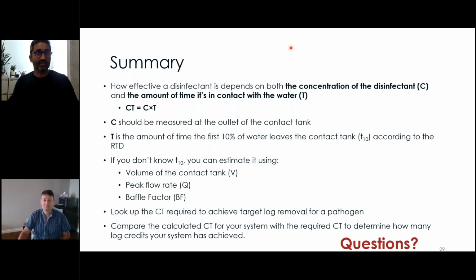If it's a small system, then maybe you have a large enough vessel that you can use to collect a volume of water, and then you can use a stopwatch to see how long it takes to fill up to a certain known volume. Based on that, you can calculate the volumetric flow rate. So the amount of volume that you're able to collect over a given amount of time, either a minute or some seconds, you can use to then calculate a volumetric flow rate. Off the top of my head, that's what I would suggest, depending on the size of your system, if that's possible.